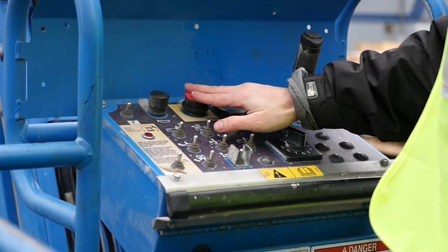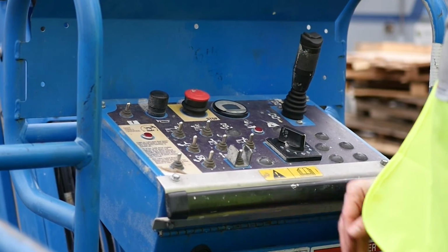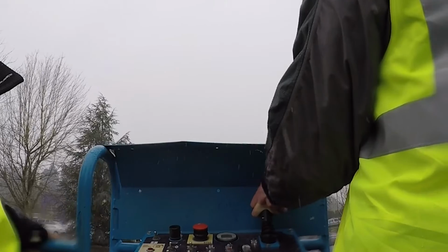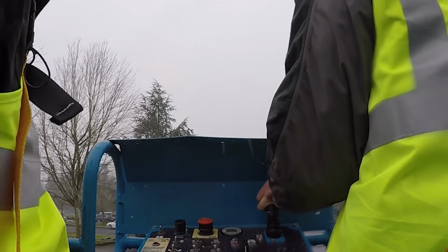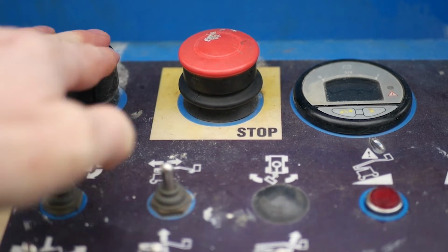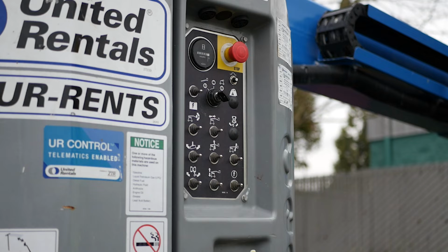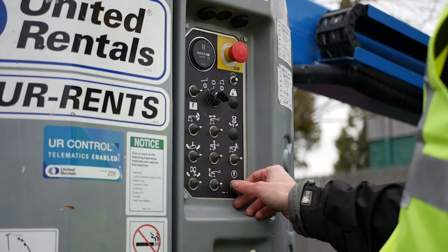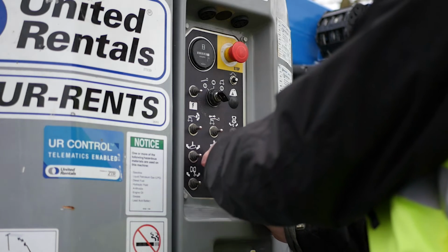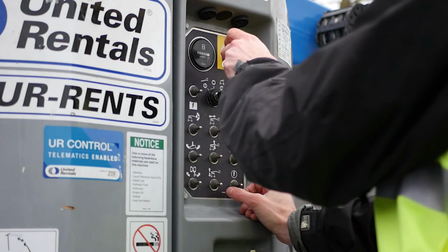Pressing the emergency stop will stop the vehicle. There is an e-stop on both control boards. If for any reason you feel unsafe, just press the e-stop, and notify a supervisor. If you find the vehicle controls unresponsive, check the e-stop on the platform and ground controller. It is likely one of them has been pressed.